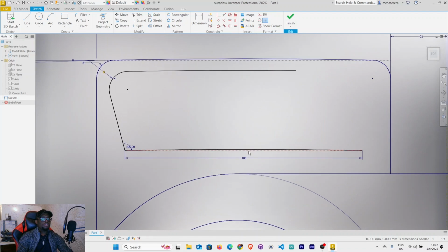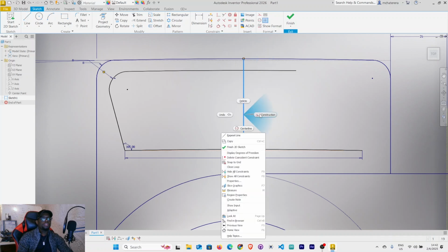Now let's draw a line of symmetry that will be connecting all these arcs. All right, so select the line 2. Let's look for the center point. So it's here with our green dot, up to there, right click OK. Press escape. Let's make this a construction line.